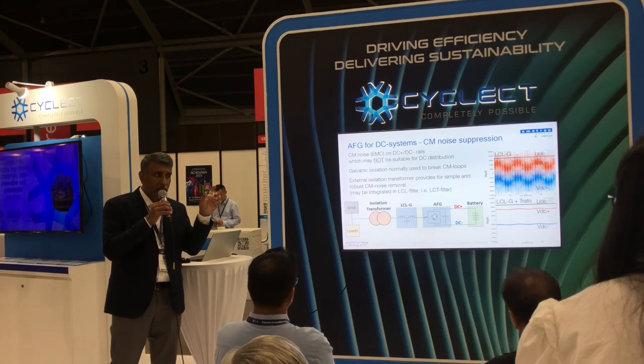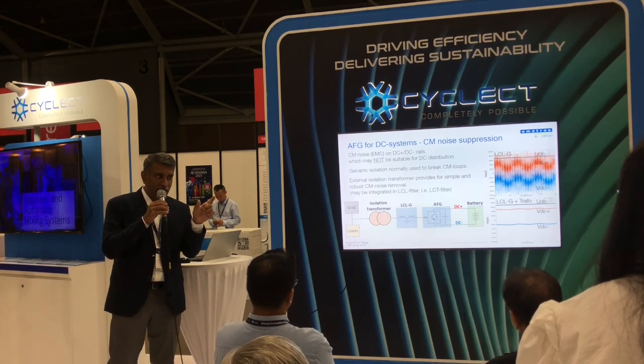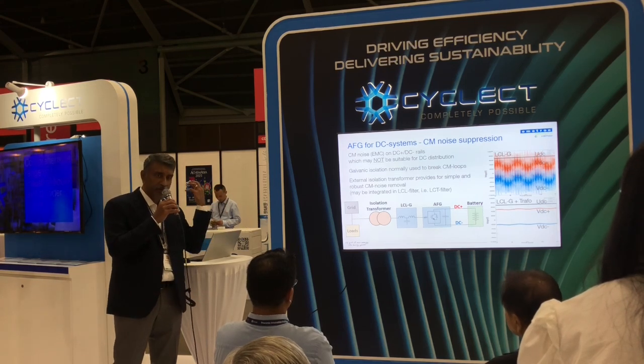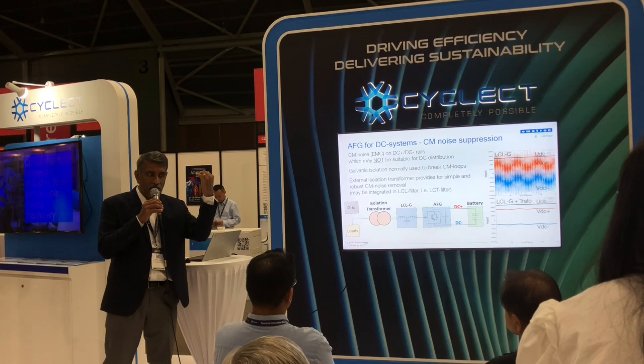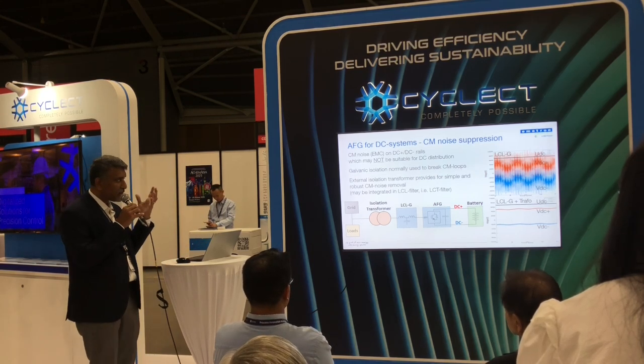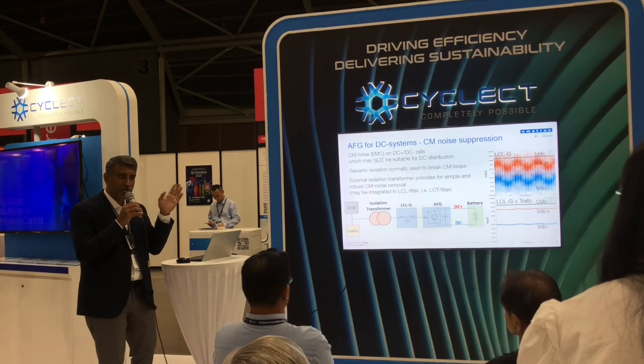So you have peak load at one time. At that time, you don't utilize power from the grid, you push power into the grid, and when the load is low on the grid, you charge your batteries. Okay, that's a power shift or a load shifting application.